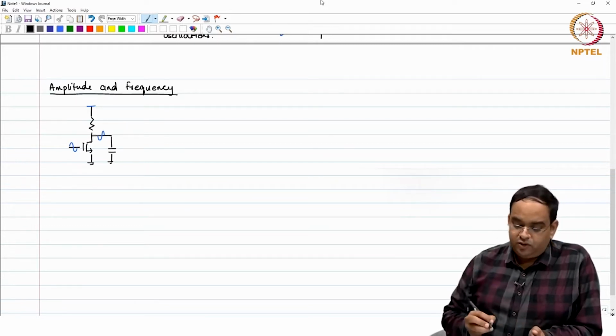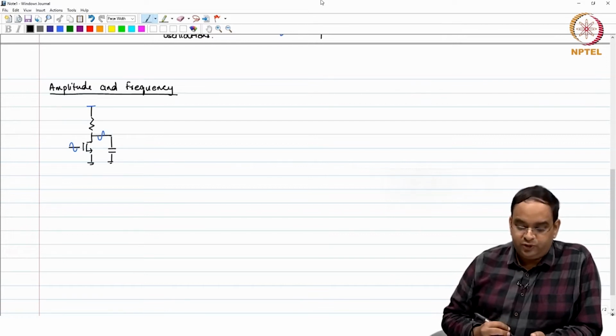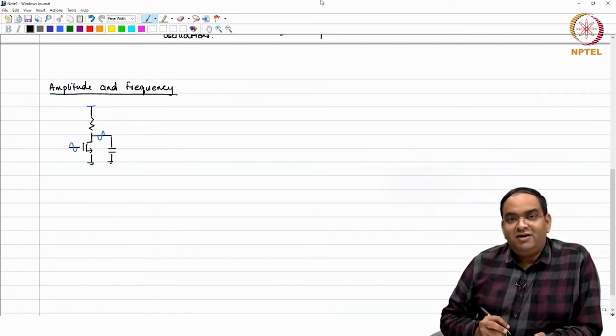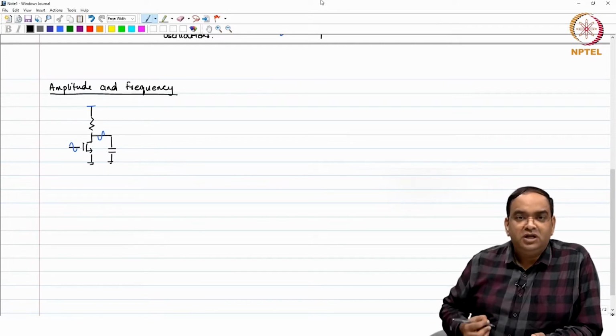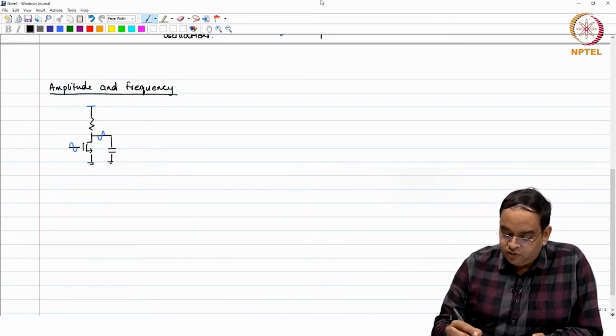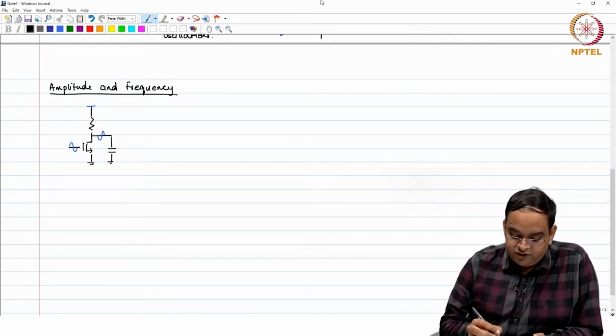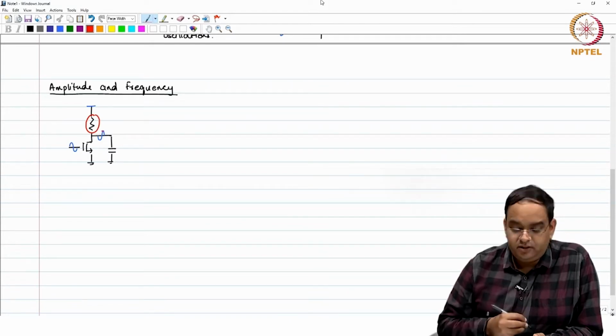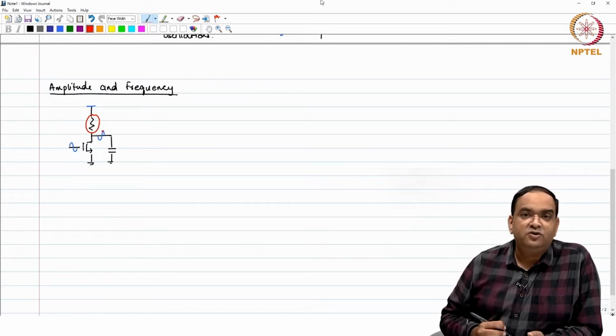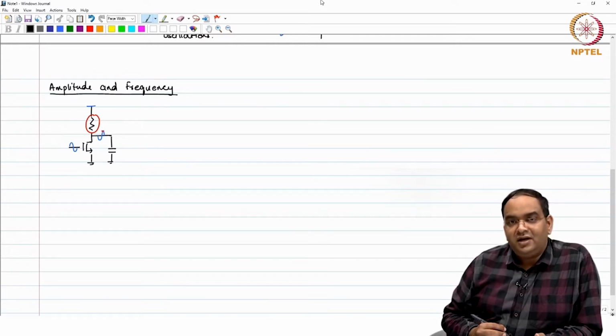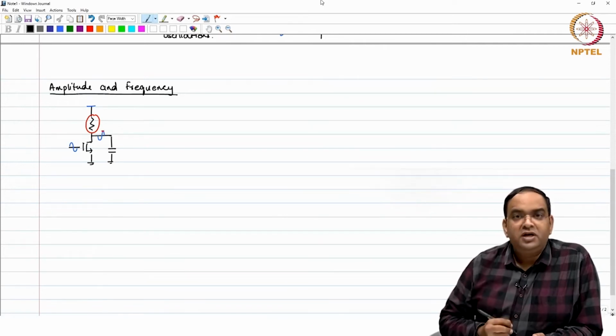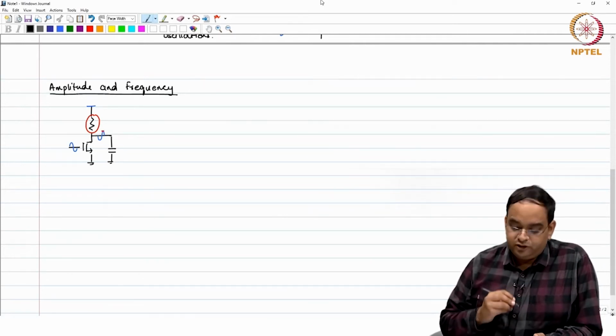Okay. So, if we would like to control the output swing, we would like to have a fixed current going through the resistor. Okay. So, fixed current, because the swing which you are producing at the output, when you have a maximum swing here, right, that time you are actually having a maximum current going through the resistance. So, if we can control the current in the RC load, then we can control the output swing.